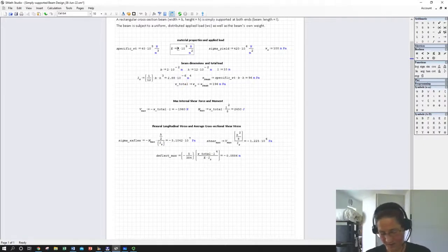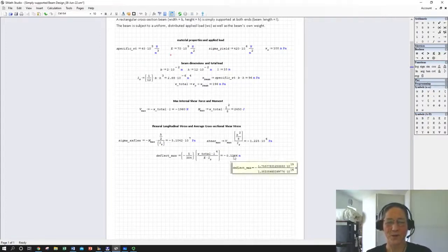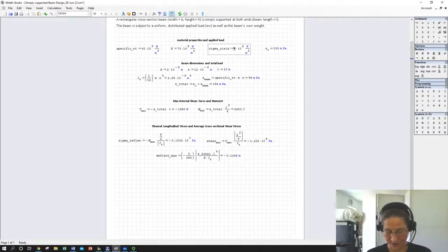So let's be conservative and say that we're going to go down from 100 to 70. So we now kind of lost a lot of the advantage that we had otherwise gained in flexion. And nice thing, if we go to a heat-treated aluminum or certainly to titanium, we might get a much higher yield stress. So if we're looking at comparing our sigma to that, we're going to have a big benefit. We're going to leave our applied load where it is.